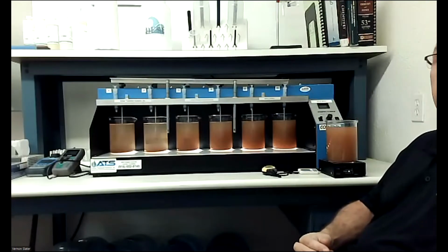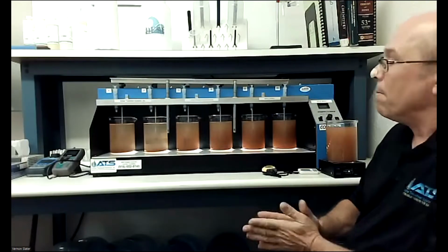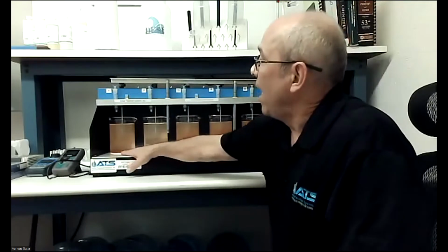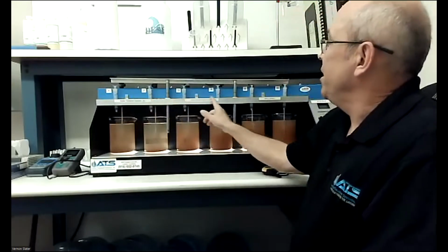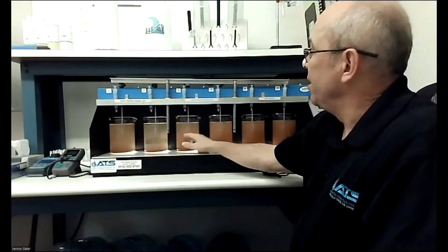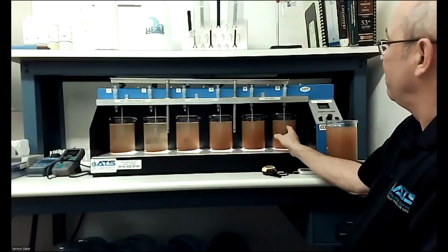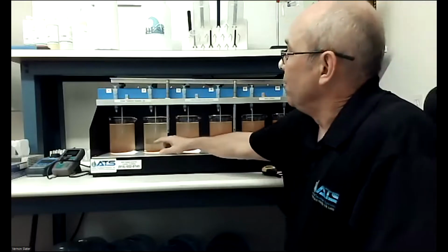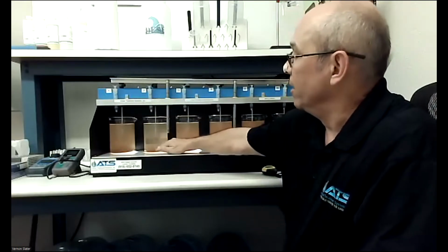So what's going on here? It shows me that I put in a different dose for each one of these: 50 parts per million, 100, 200, 300, 400, 500. And I'm seeing here at 100 parts per million, I'm getting very good settling going on.